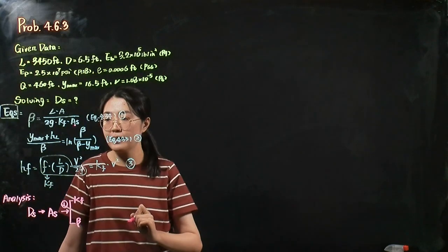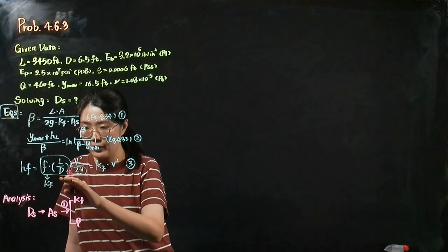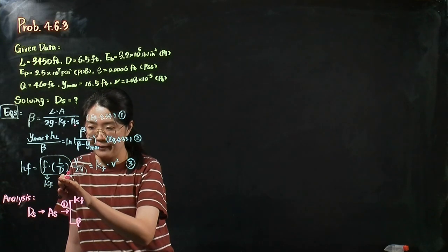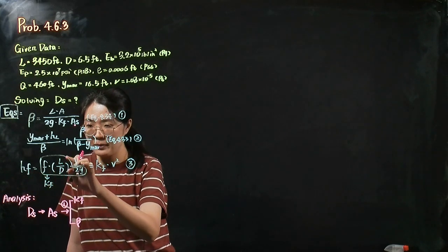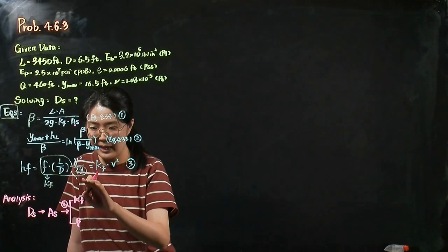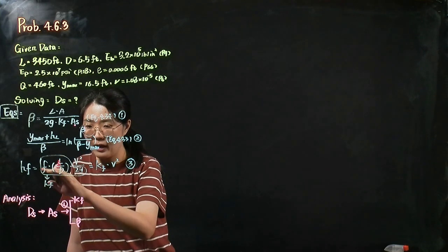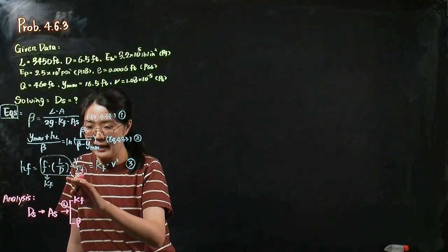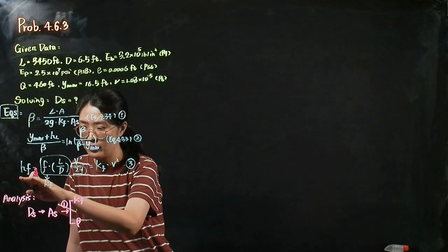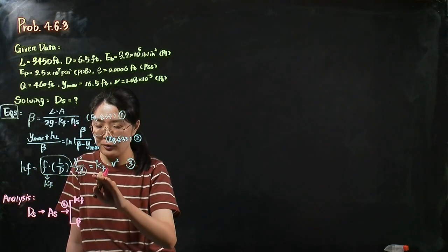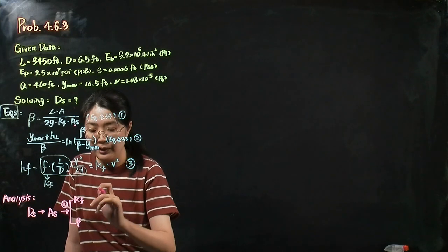Let's look at K sub F first. If we write down the Darcy-Weisbach equation, we can find the friction loss. It equals the friction factor times L over D times the velocity head. If we bring all the constant values together and set them equal to K sub F, then we can rewrite the Darcy-Weisbach equation. It equals K sub F times velocity squared.